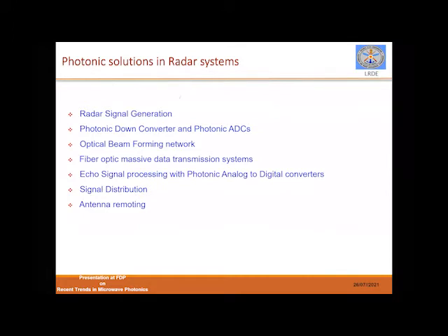What exactly I wanted to tell you here is which are all the areas where we can apply photonics in a radar system. It is basically in the signal generation part, or we can use it for photonic down converters and photonic ADC applications, for beamforming applications, and for data transmission and echo signal processing. Basically, get the RF signal, digitize it and further process it in a radar, and for antenna remoting applications.